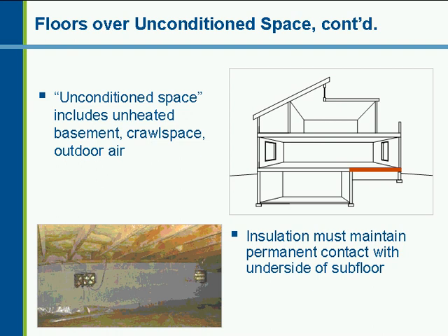Floors over unconditioned space, note that the definition of unconditioned space would include outdoor air, it would include an unconditioned crawl space, an unheated basement, a garage underneath, anything like that that is not directly conditioned.